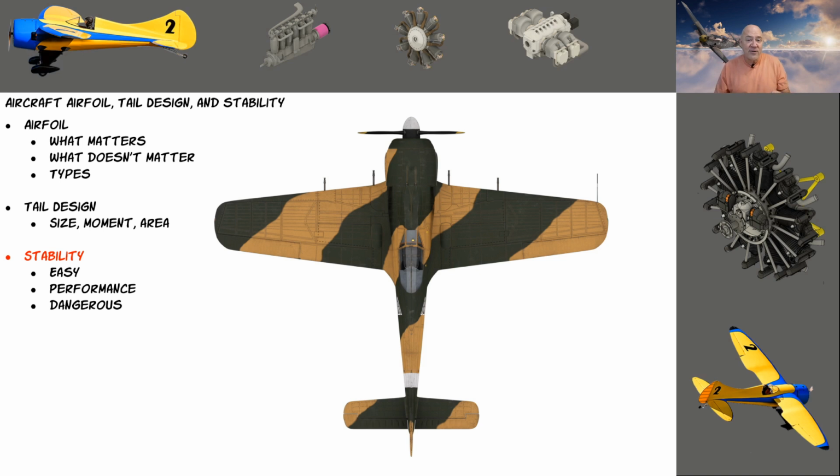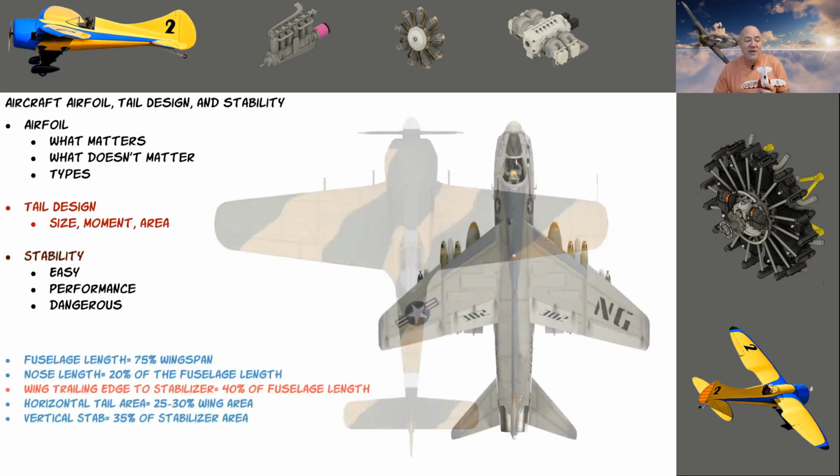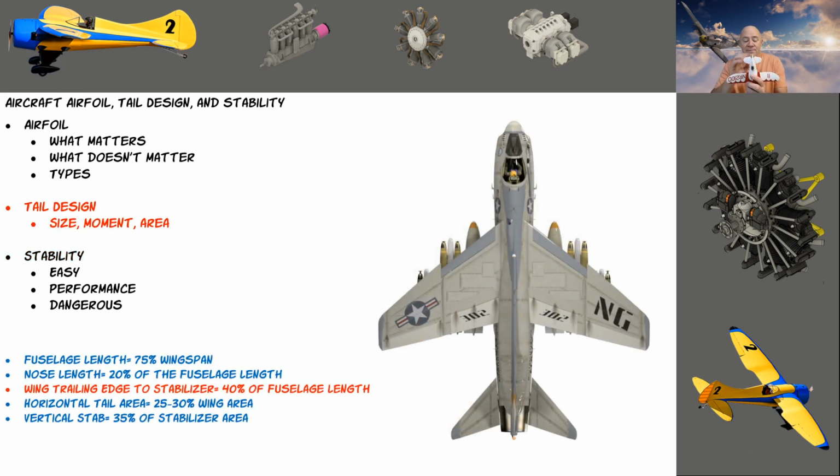And I'm going to always refer to a little bit of the tail, because look, the tail isn't any kind of special. Hang on, let me back up for a minute before I jump into this. There is no magic in the tail of the airplane. It is a crowbar. It's a cantilever that's trying to control the pitch at the center of gravity of the wing. Okay? So if you think about where the center of gravity on that wing is, you got a motor out here and you got a tail.